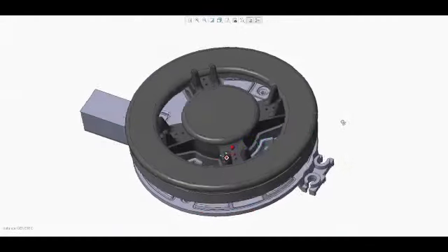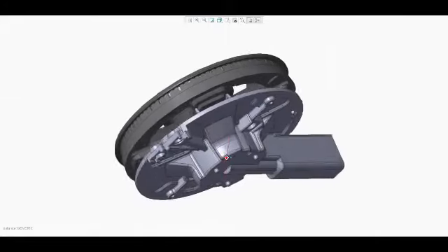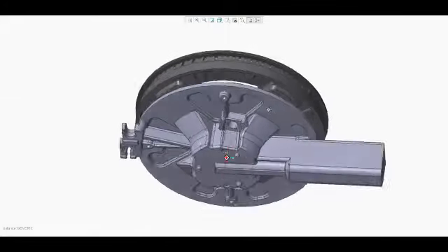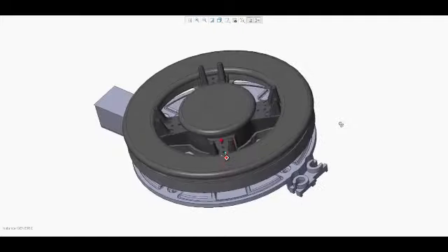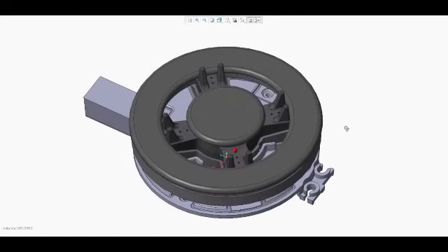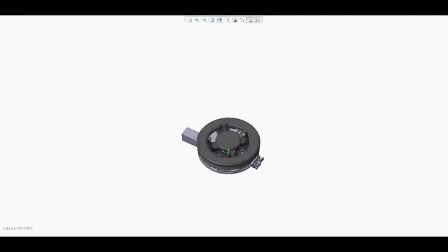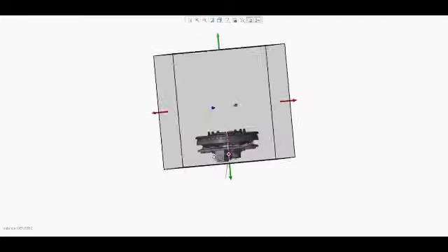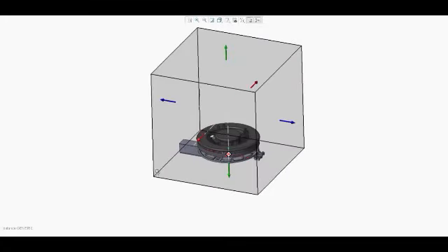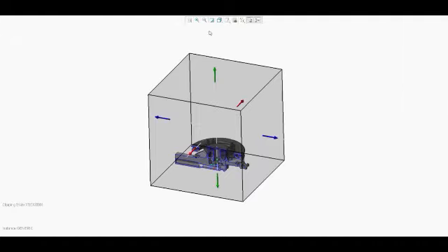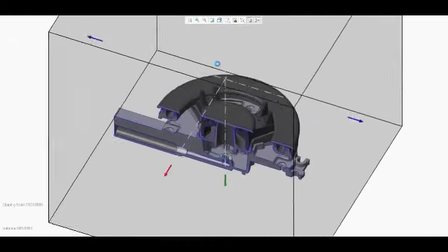For this demonstration of the combustion capabilities of FloEFD, we'll be using a domestic burner ring which uses methane for fuel. There is an inner and outer ring and an additional igniter part which we'll cover later. This analysis will be performed in two steps: the cold mixing in steady state and the transient burning phase. The computational domain size for the mixing analysis can be seen here.